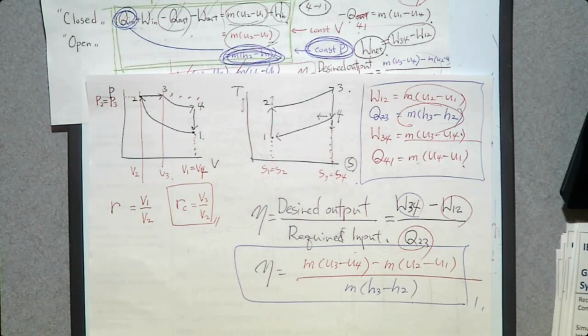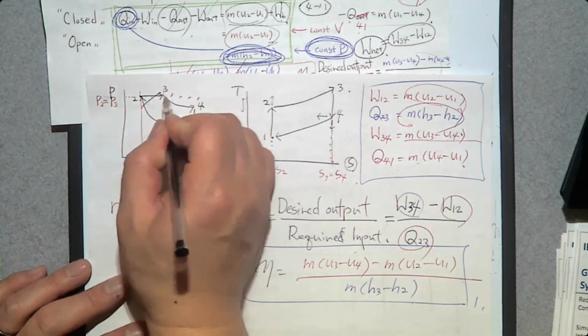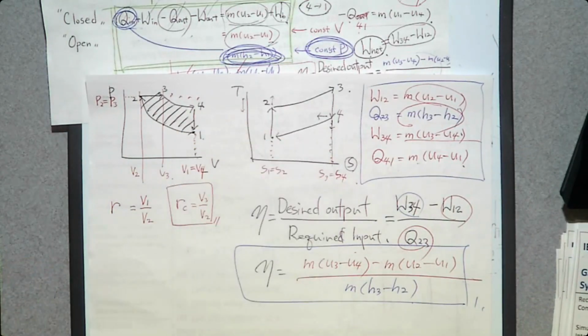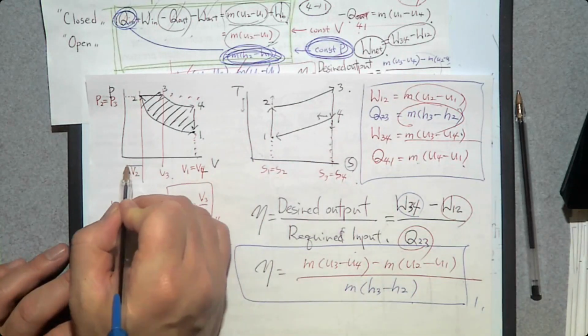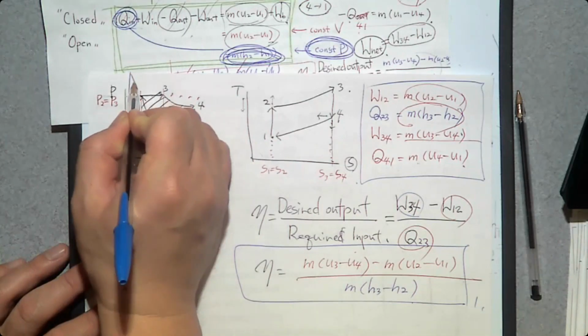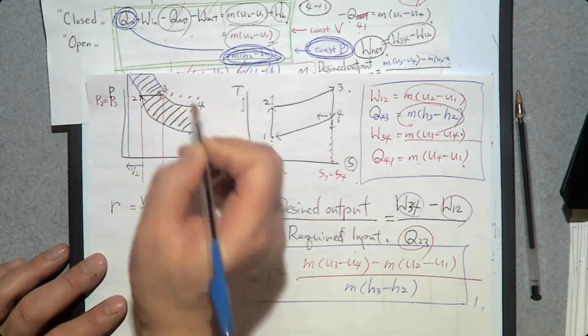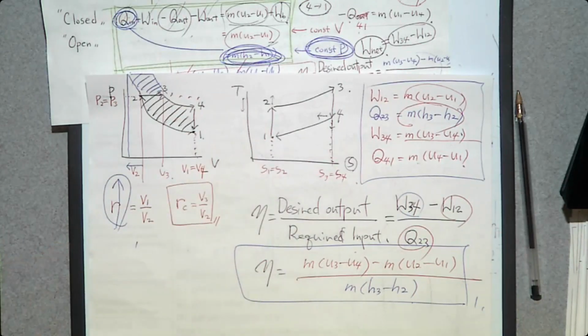Then, as we discussed in the previous Otto cycle analysis, the enclosed area determines the net work that you produce. So how can you increase the net work? You can compress more, even further from here. Then you can add this much if you increase the compression ratio. Can we do that? Yes, when you have a diesel cycle.